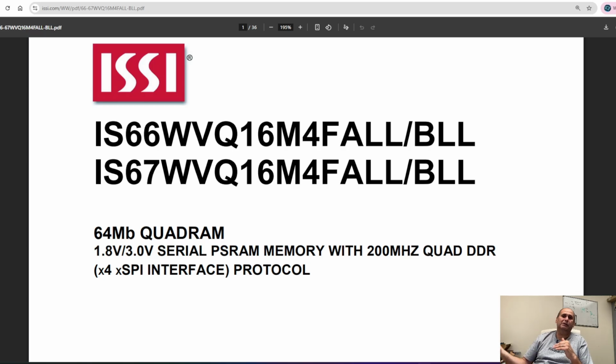So you need to have a pixel coming at 148 megs. Now this part is 200 megs, 4 bits, but it's DDR. So you get a penalty. You're not going to get 200 megahertz reading out of this memory. No way. Because you have all that penalty to set up, and you're going to get less. So now it's actually worse. You're going to get less for other reasons, because you need to have writes from time to time.